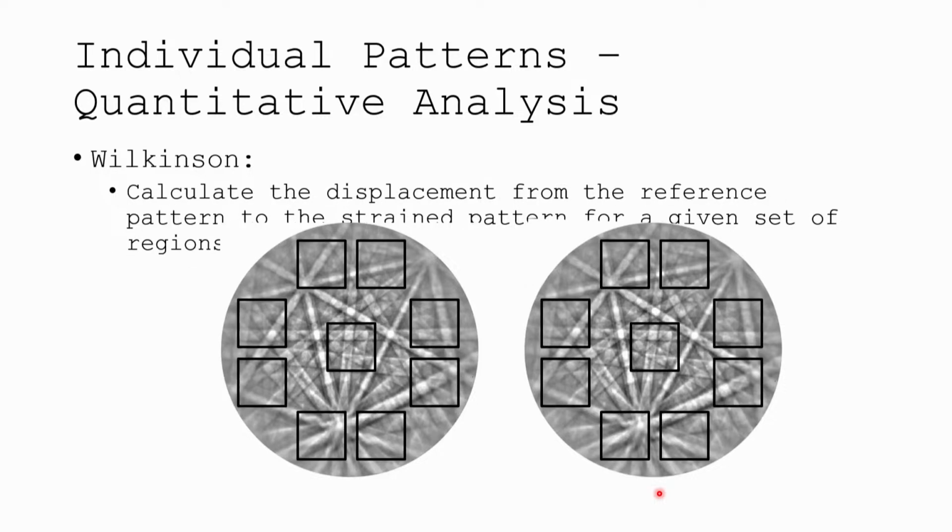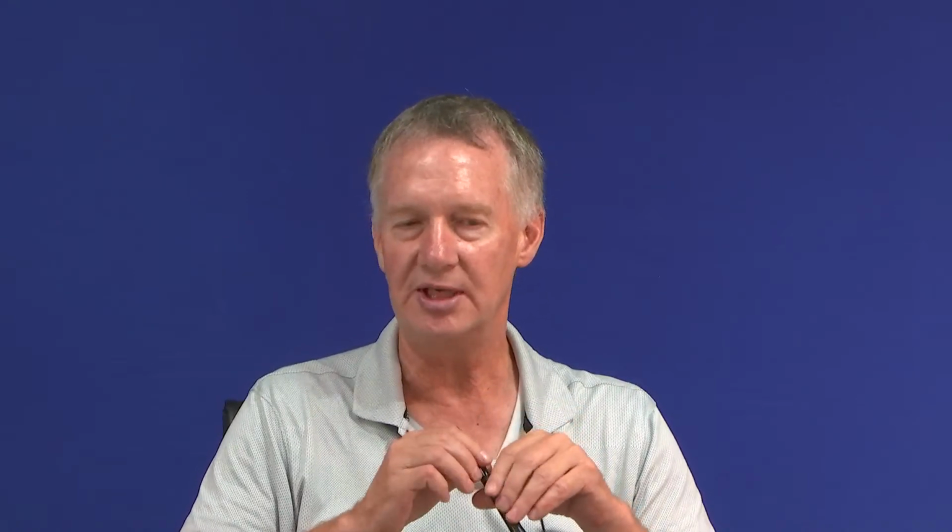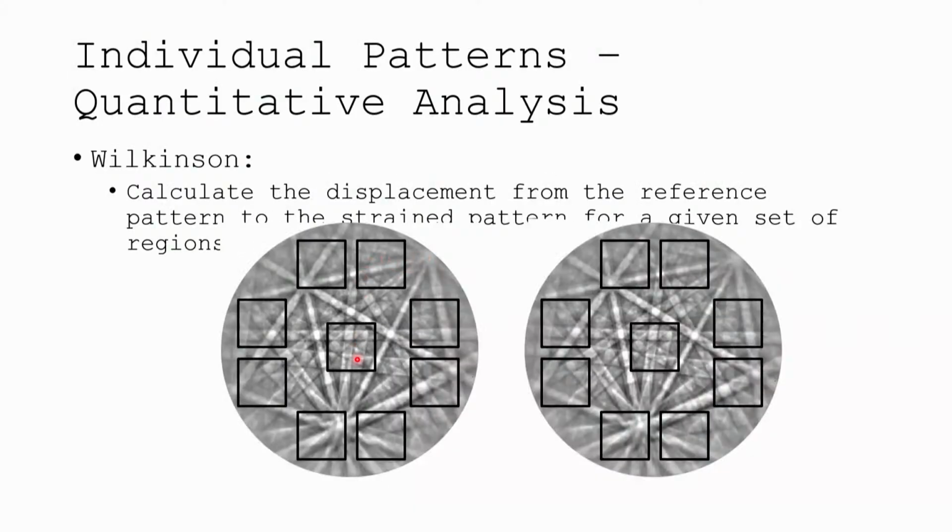Okay. Now, high resolution EBSD. Maybe you've heard of this term, HREBSD. They don't mean high spatial resolution, they mean high angular resolution. I don't like the term; I usually call it cross-correlation EBSD instead of high-res EBSD. But this is what happens. You take a pattern that we call a strain-free reference pattern. If you have a strained material, where do you get a strain-free reference in that strained material?